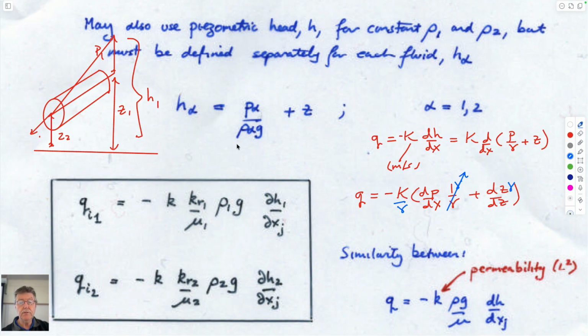And we also know that we can link hydraulic conductivity, density of the fluid, gravity, is equal to permeability divided by viscosity as a standard result. The units of this link up. This is in meters squared. This is in Pascal seconds, SI. This is in meters per second.